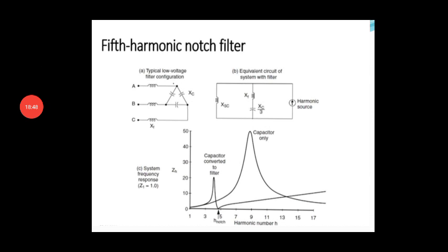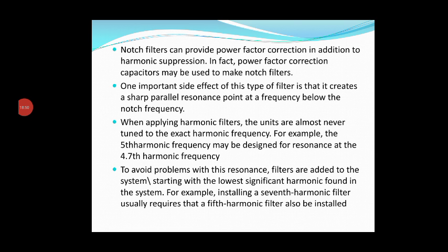Okay, this is what a notch filter is about. A notch filter can provide power factor correction in addition to the harmonic suppression. In fact, power factor correction capacitors may be used to make notch filters also.